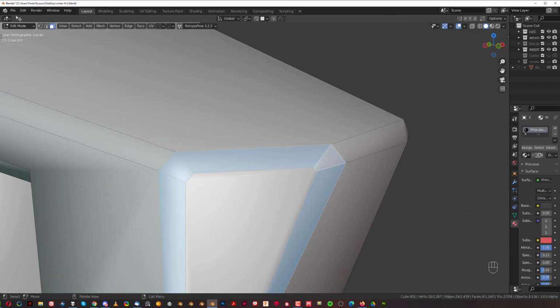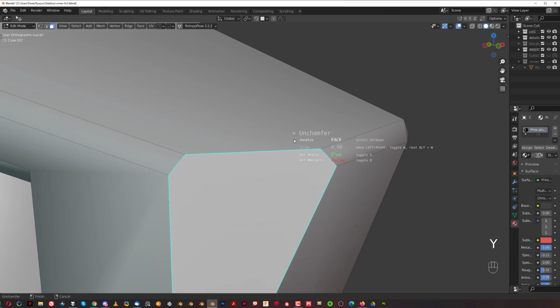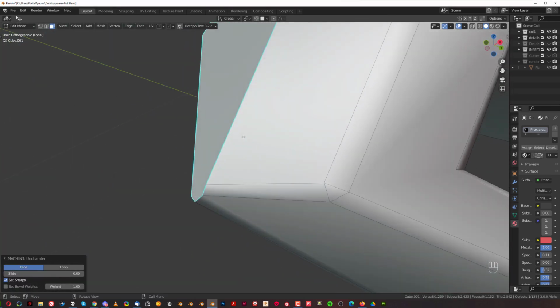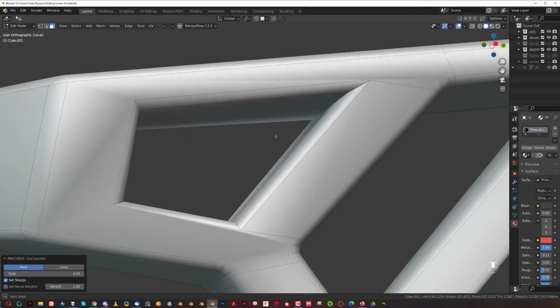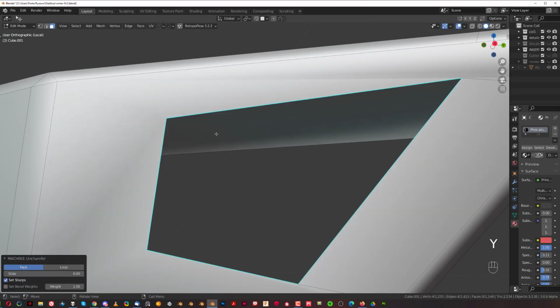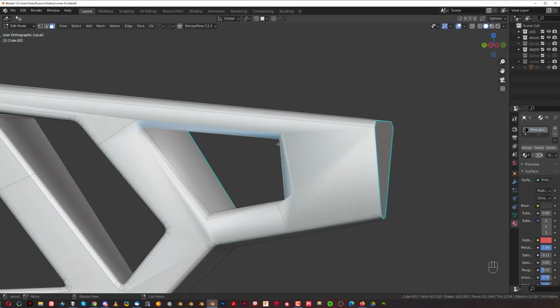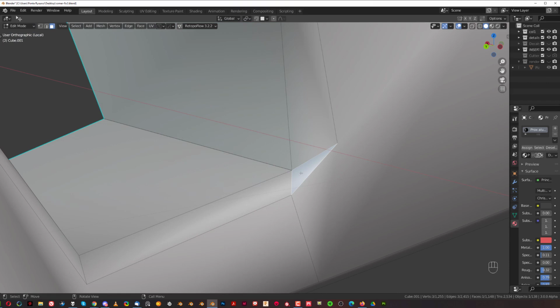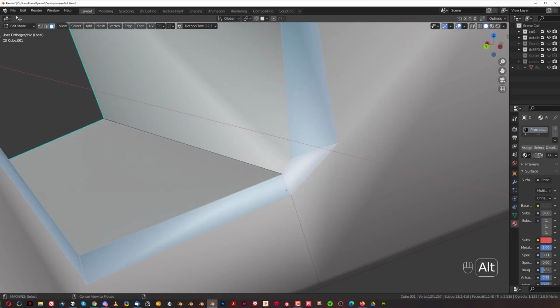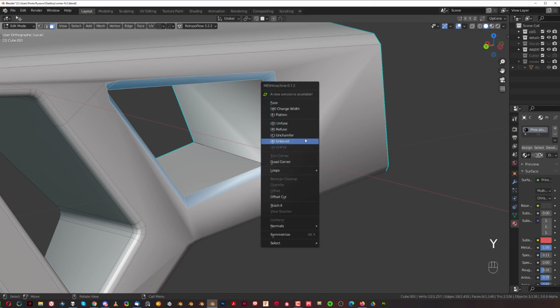Then you select everything, Y, and unchamfer, and boom, you got the line. And this is how I would fix the entire mesh, guys, okay? So the same here, select this and Y and chamfer, right? And select here this one. This one is messed up here. We need a quad corner here, so quad corner, and then select everything and unchamfer.